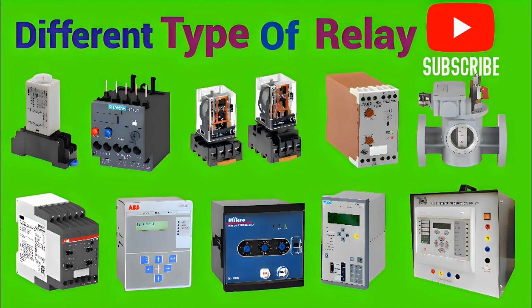Starter system. In automobiles with larger engines or diesel engines, the starter motor requires a significant amount of current to crank the engine. Relays are utilized in the starter circuit to handle this high current. When the ignition key is turned to the start position, the relay is activated, allowing the high current from the battery to flow to the starter motor.